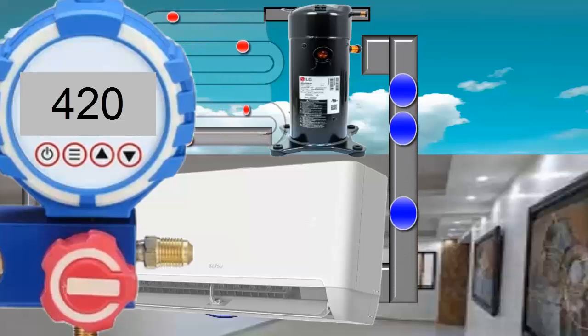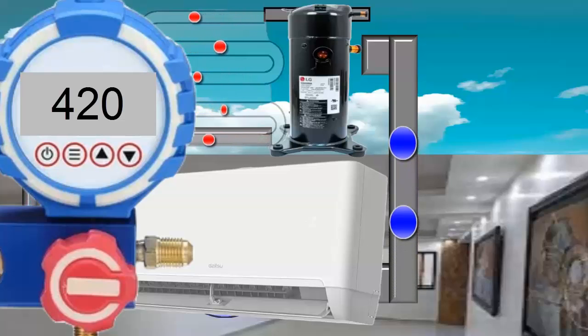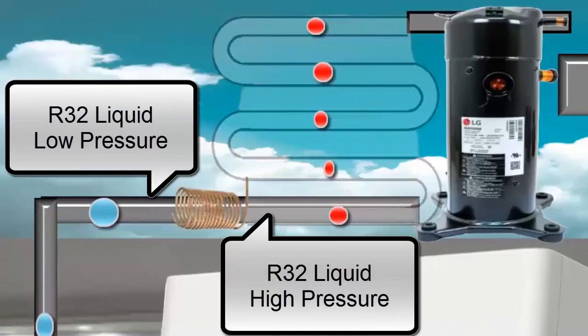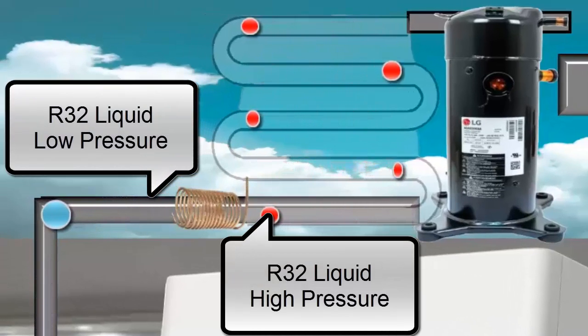The gas pressure after the compressor in the condenser unit generally exceeds 400 pounds per square inch, psi, and must be measured with the red pressure gauge. The R32 leaves the condenser unit in a liquid state, but with high pressure.